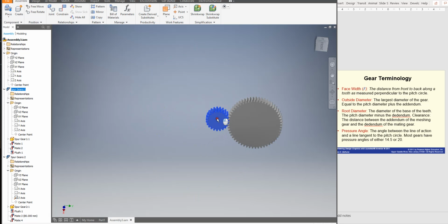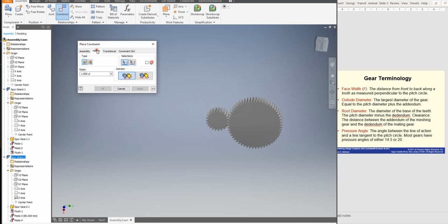But before that, we have to make a relation. If I remember, the smaller gear is the drive gear. The right one is the driven gear. So how can I relate them? What type of constraint can we add? It is a motion constraint. I see we have two types: rotation and translation. Here we have rotation. I will choose rotation.